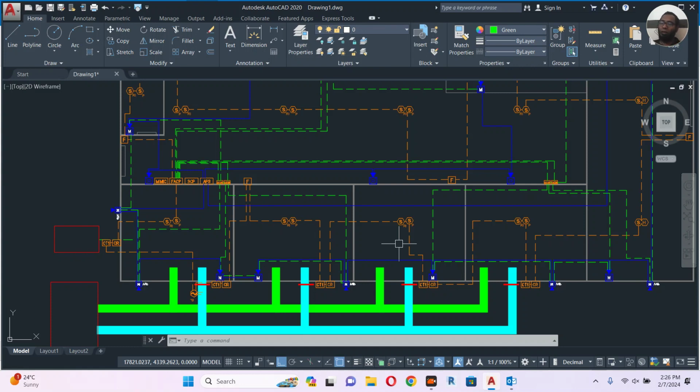So how will the access control panel know? I have to make all the doors open because there is a fire, and the access control panel doesn't have any fire sensing modules or anything. So we will give one control relay module to the access control panel and connect it.